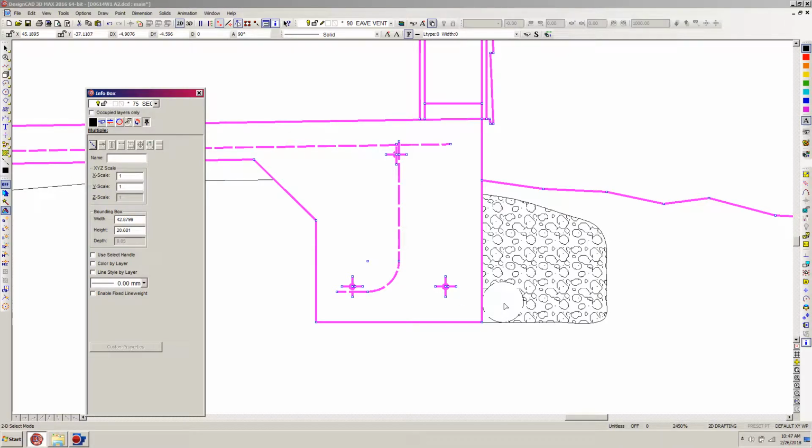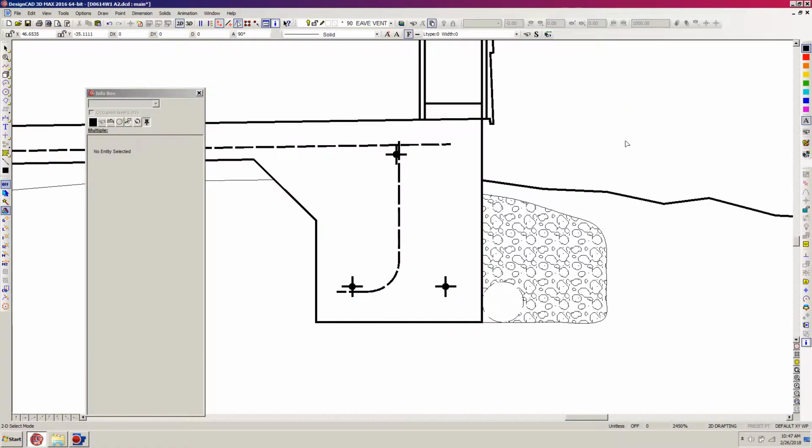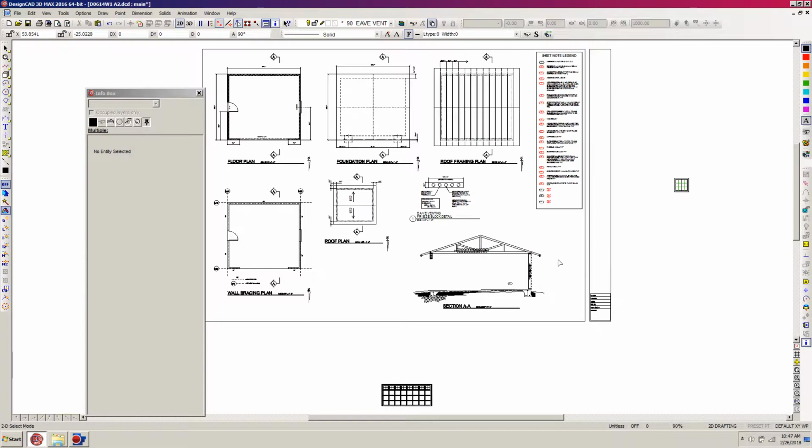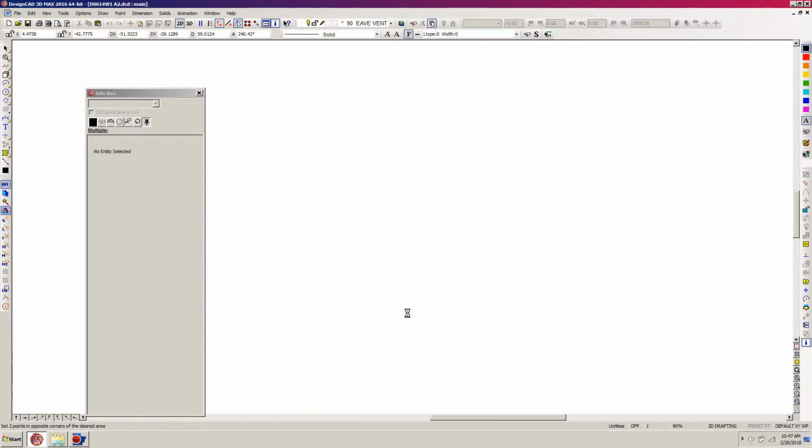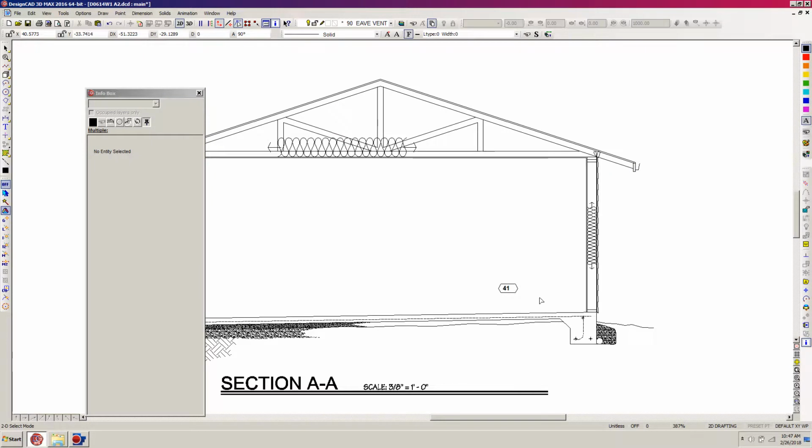So anyway, I'm going to click on the drawing somewhere, hit Control W and zoom on out, then hit Z to zoom up into the section drawing here, and now I'm going to hit the greater than or Shift period to create the arrow, and I want to be in layer 76. Actually, I can change those after the fact. So maybe I won't worry about that right now because I'm going to be doing sheet notes and various drawings on this sheet.